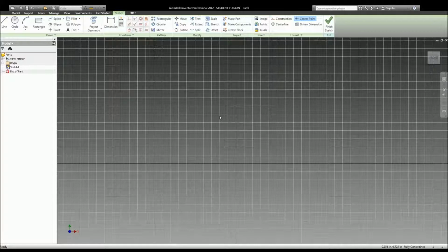So, move, it's exactly as it sounds. You click the move function. You can either click to move by the side or click each side of the object and then click whatever you want your base point. You can move it around. You can also use it to copy. So if I want to copy the object based on corners like so. Oh, no, that's not corners. So I want to make a copy of this object from this base point. Boom. I now have a copy of the object.